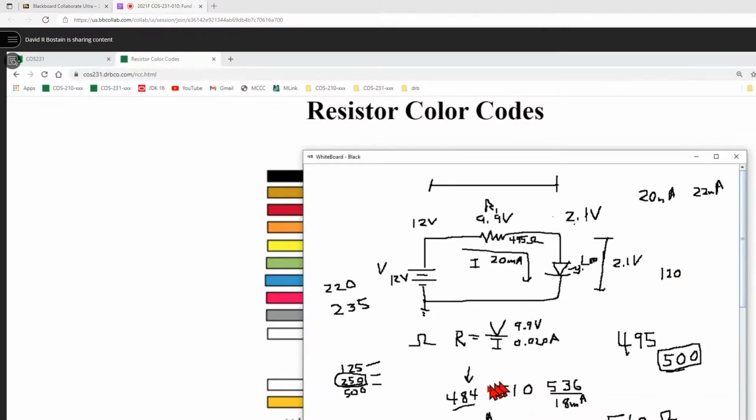So if I said, okay, I got one and it came out to be 120 milliwatts is what it's going to use on this guy. That's awfully close to 125. So I certainly wouldn't use a 125 milliwatt resistor. I'd use a 250 milliwatt resistor because this is just too close. Again, it's one of those, you have to have done it for years in order to actually be always right. And still you'll make mistakes.